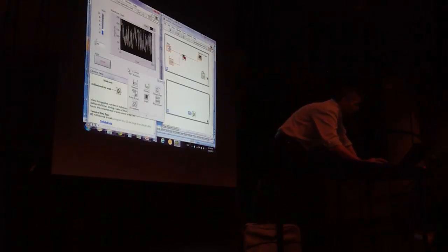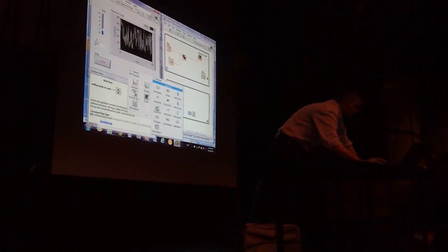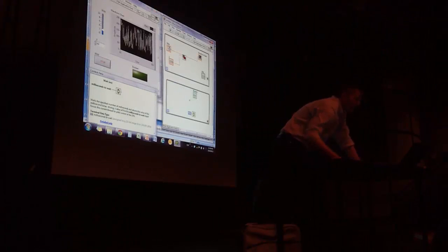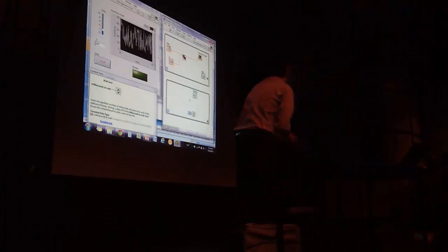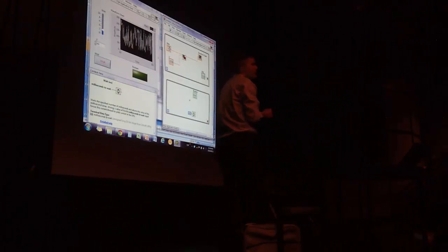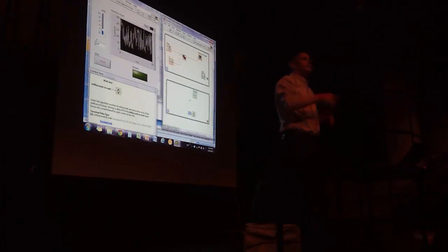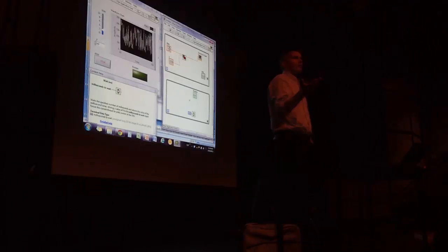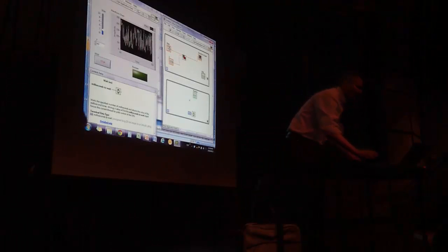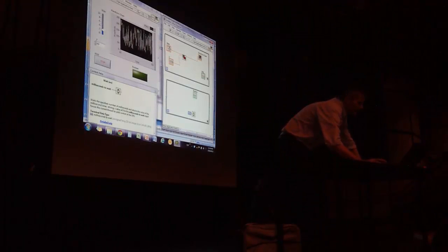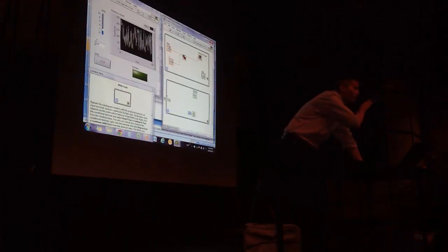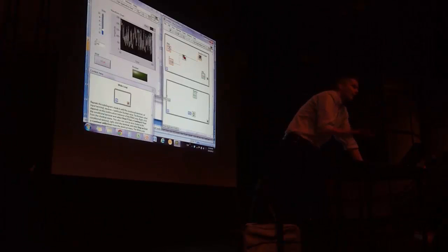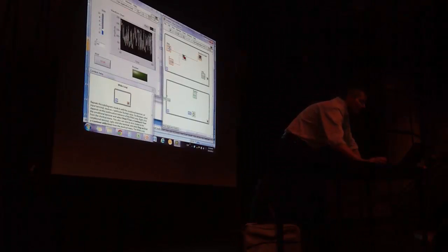And I want to display an LED here, for example. So I drop down here the LED. And now I just want to make it blink. So the easiest way is, whenever it goes through the loop, it should invert the state of the LED. And how do I do this? There is something called shift register, and I will show you some links later that talk a little bit more in depth about the advanced programming concepts.